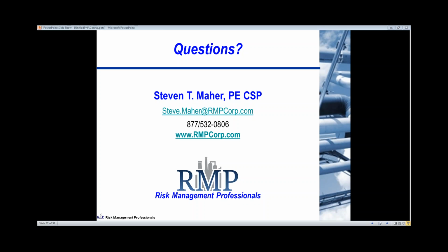We have a question also. Do you recommend always doing a LOPA in conjunction with the HAZOP? There seems to be two distinct opinions about this. Some say no, a HAZOP is sufficient, and a LOPA can make a HAZOP so large it becomes ineffective. And others believe that a LOPA is beneficial, especially when added to definite aspects of a HAZOP. Your opinion? Okay, that's a great question.